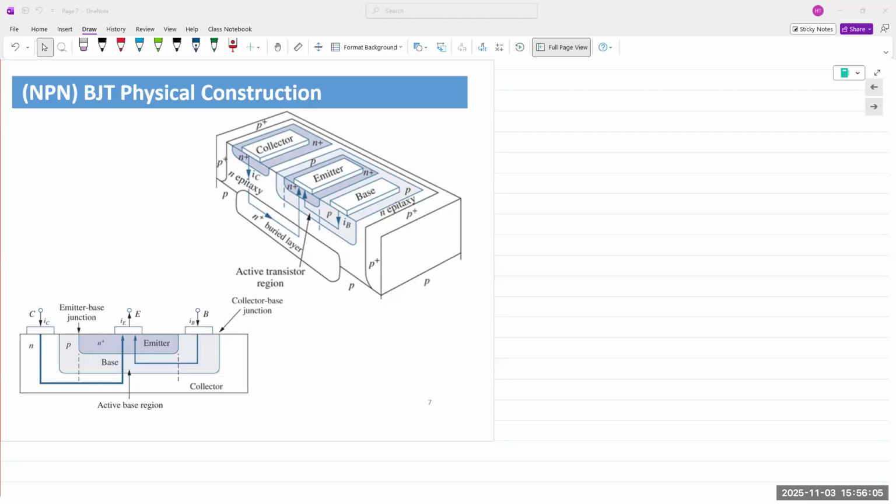So the base current is very, very small, typically in microamps. Okay, just because the doping is low, so the number of holes is less, number of carriers is less. So the base current is very low. Emitter current is slightly higher. I wouldn't say slightly, it's actually a lot higher. So probably in milliamps compared to microamps. So thousands of times greater than the base current.